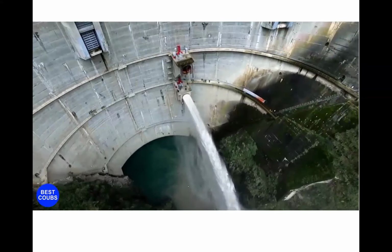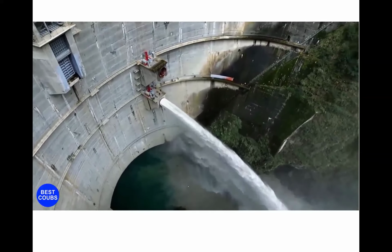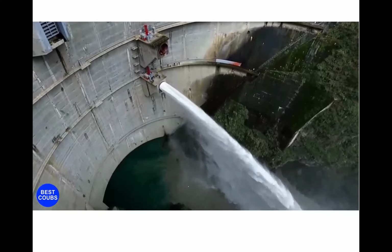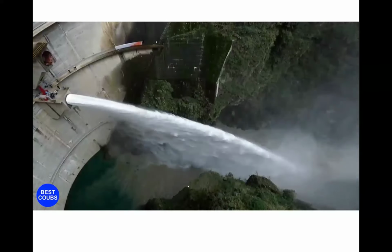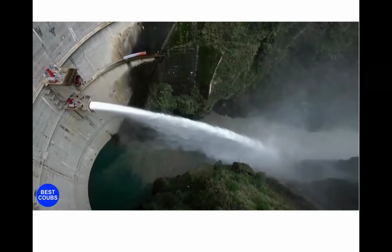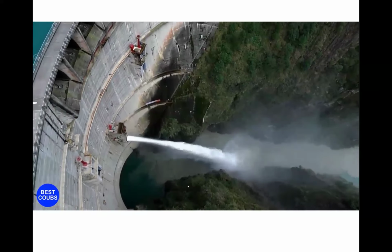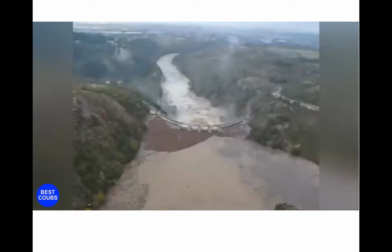And yeah, this is another case. This is an outlet from a dam. So that's a dam, and that pipe coming out is an outlet for discharging water. And you see people on that platform. And the diameter of that jet is probably easily 5-6 meters. And the flow coming out is extremely fast, maybe 30 meters a second or something, which is very fast for water. Yeah, this one might be for just discharging water from this reservoir for different purposes, which I'm going to talk about a little bit in a couple of slides. But yeah, just to give you, again, some scales.